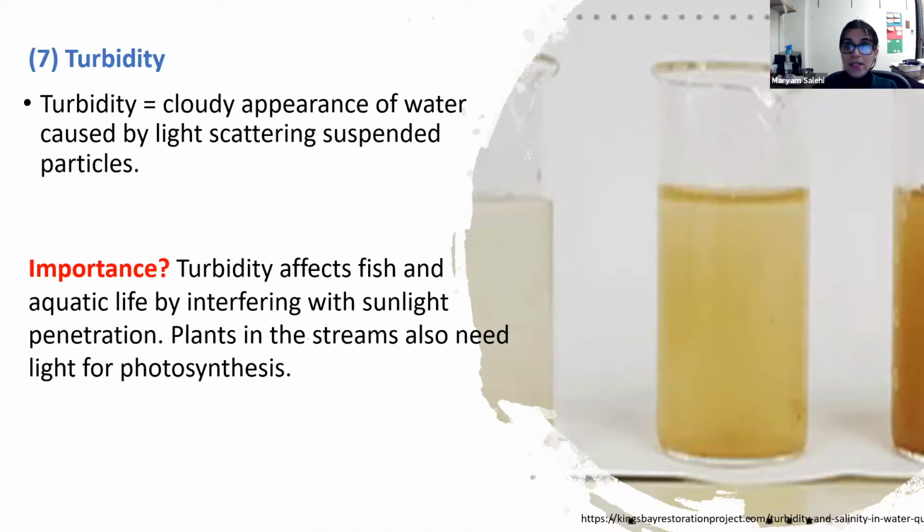Turbidity is also important because if you are using the surface water as the source of our drinking water, when we have higher turbidity, the water treatment plant needs to adjust their treatment practices to remove this turbidity. And the turbidity is fluctuating. For example, if we have a rainy day, after that we are going to have higher turbidity in the surface water. And then water treatment plants need to adjust their treatment practices because they got higher turbidity after the rain.